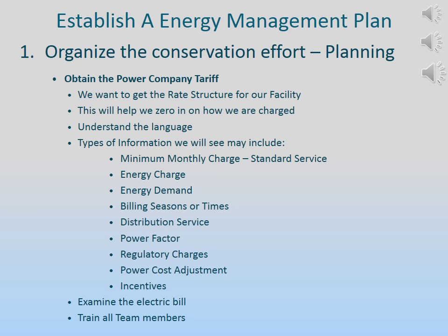Obtain the power company tariff. It is important to get the power company rate structure for our facility. The power company provides a tariff that has multiple rate structures in it. We should focus on the one that applies to us. This will help us zero in on how we are charged.